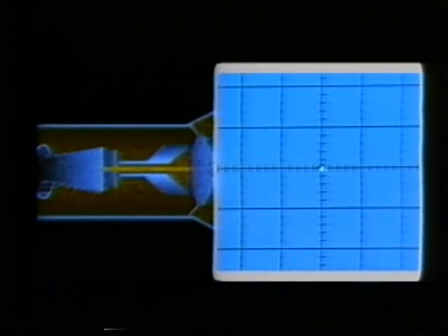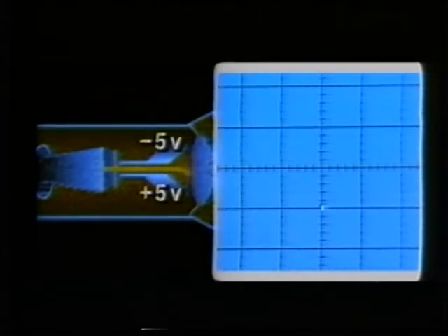So to move the signal up one division, instead of attracting it with a 10 volts positive signal, we can apply a 5 volts negative signal to one deflection plate, which essentially pushes the beam away, and apply 5 positive volts to the other deflection plate to pull the beam. This concept is called push-pull. The process is used primarily to improve the linearity of the display and allows accurate measurements over the entire viewing area. Push-pull signals are equal in amplitude and opposite in polarity.